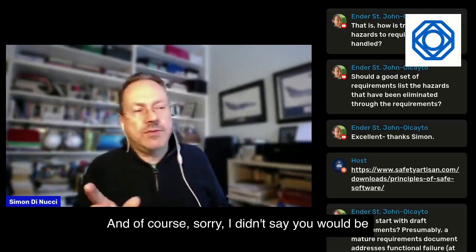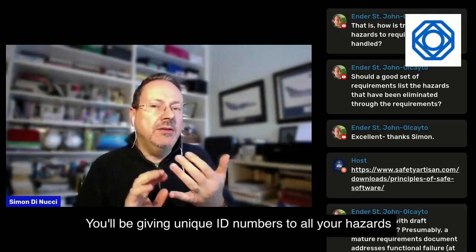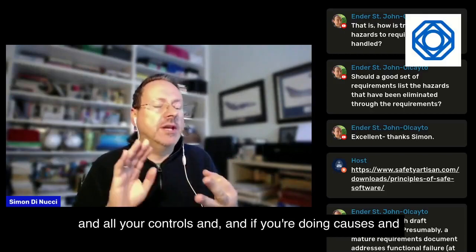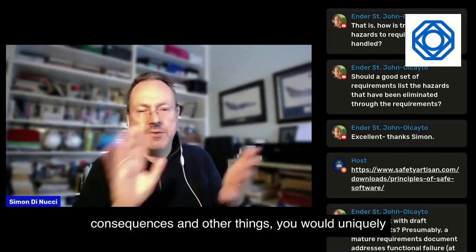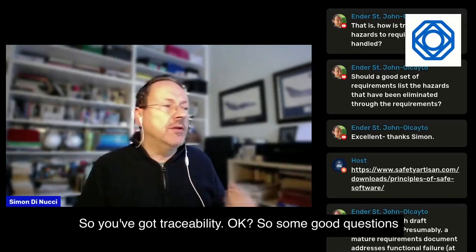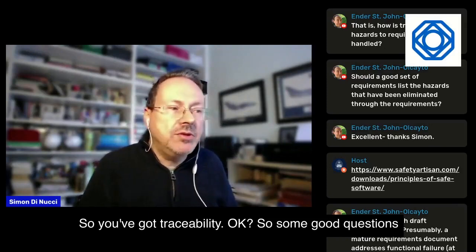Okay, and of course, sorry, I didn't say, you would be giving unique ID numbers to all your hazards and all your controls, and if you're doing causes and consequences and other things, you would uniquely number all of them, so you've got traceability. Okay, so some good questions there.